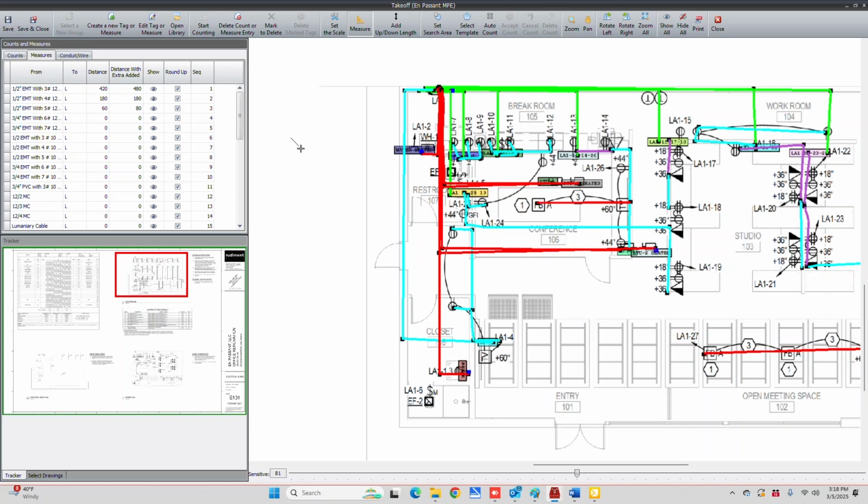Some people don't do it at all. But I like to catch 3 home runs per circuit whenever I can. That's 3 hots, 3 neutrals, and a ground. That's 7 wires. When you leave there to catch 2 more circuits, it'll be 5 wires. And when you leave there for the last one, it'll be 3 wires. So all that should make pretty good sense.